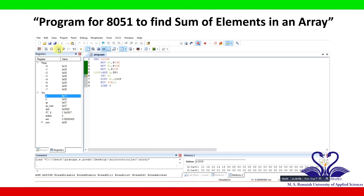So once it gets added up, the accumulator will be having the value 11, and it is shown here. So next step, when it gets executed, INC R0. R0 was initially 30H. Now once it gets incremented, +1 will be added. So 30 + 1 becomes 31H. So this 31H is loaded into R0 now. Then DJNZ R1, loop, which means that R1 is loaded with 05, which means that there are 5 numbers which we are going to add.